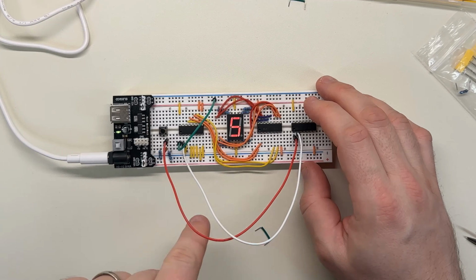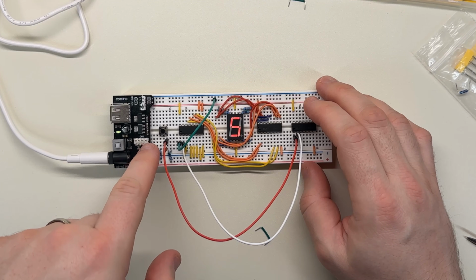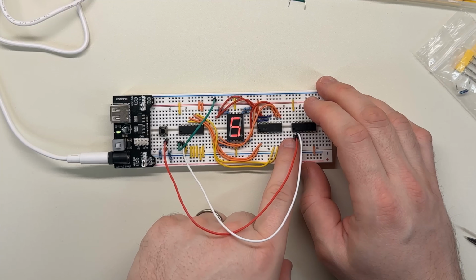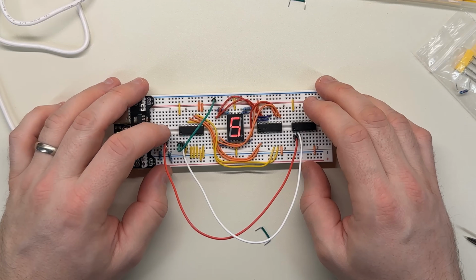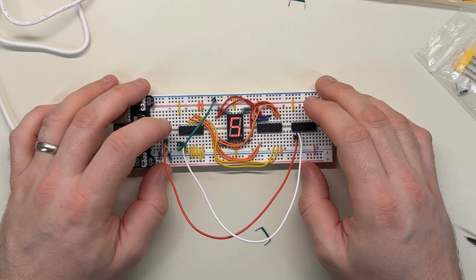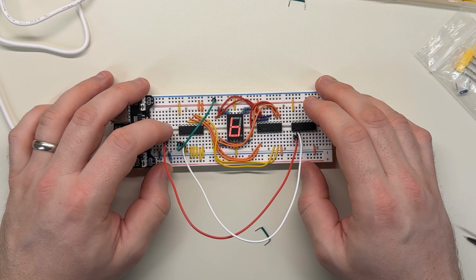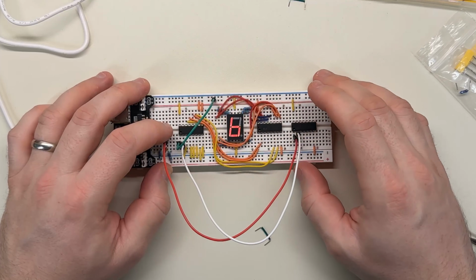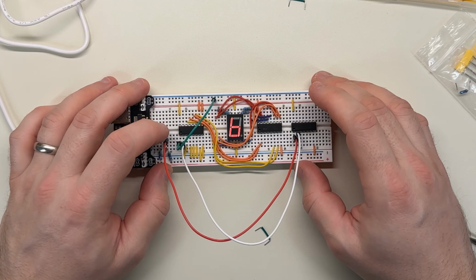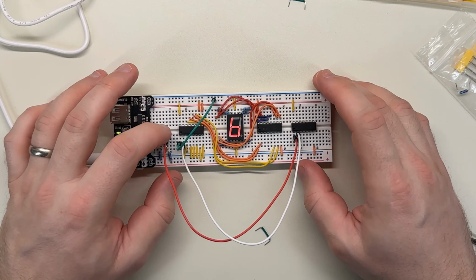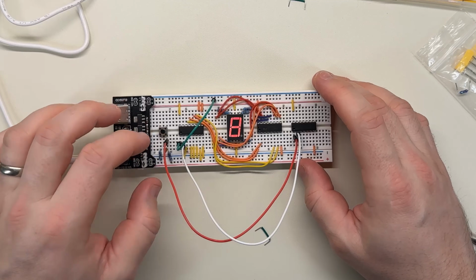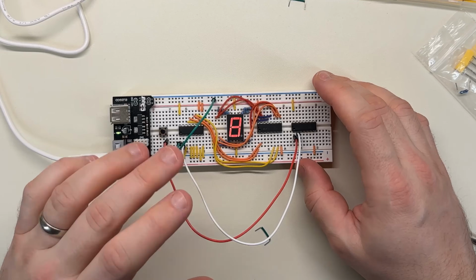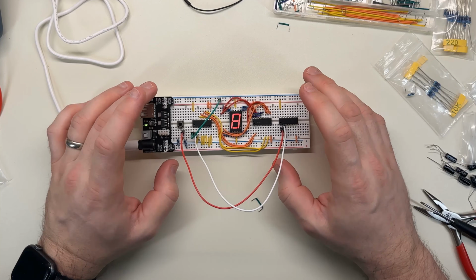Because the moment this gets the signal over here, it gets inverted and sent to the counter, and now it goes from, I think, high to low when I push it, and I think this counts on the lower edge. And so ironically, that may have made the bounce worse, because my theory is that the bouncing is worse when I first press it down and not so bad when I release it, because of how this switch is constructed. I might be wrong about that, but I think that might be what's going on.